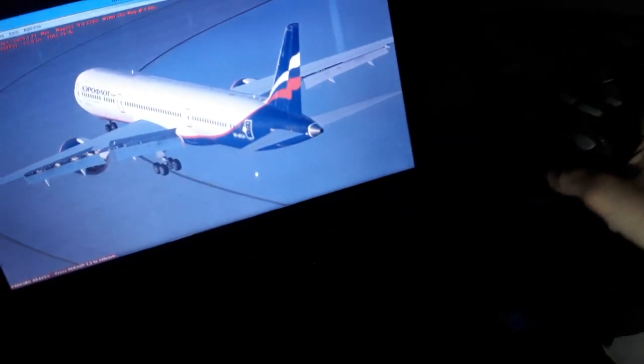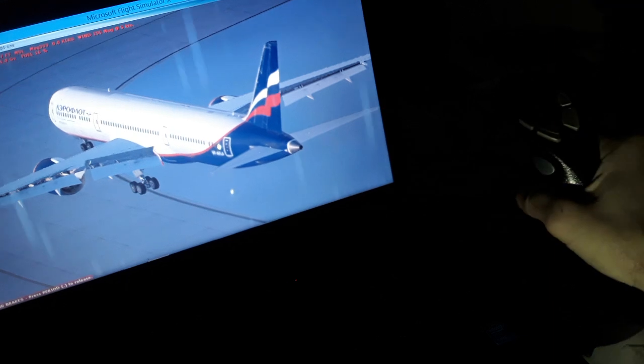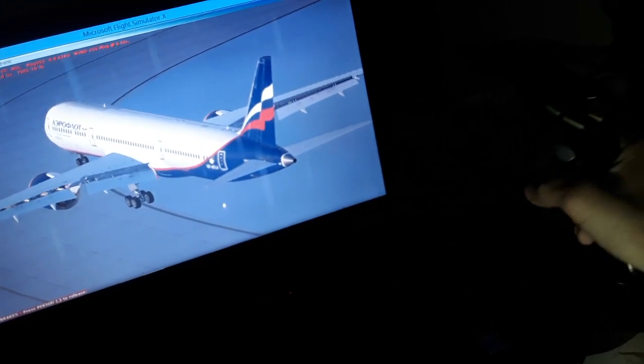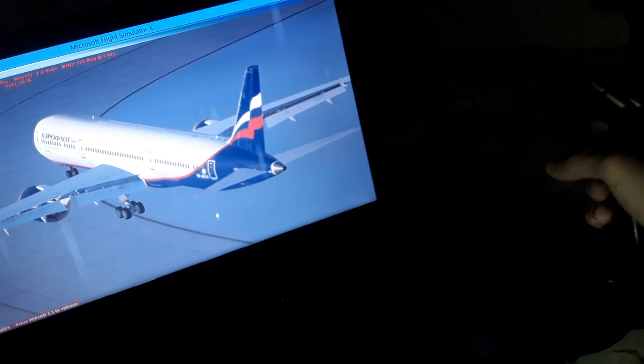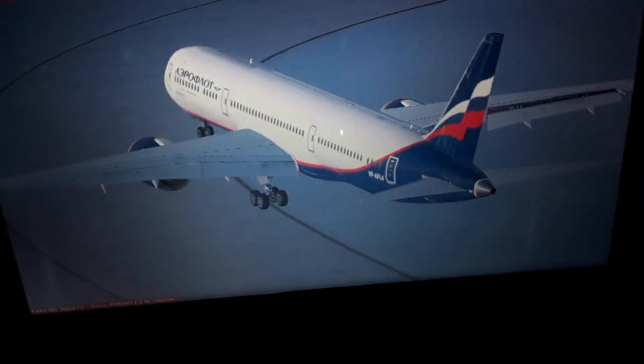We can make in the Airbus the left and right side stick turns. Use the ailerons and the spoilers, inner ailerons and outer ailerons, and also spoilers. So we have in the Boeing the flaperons, ailerons and spoilers instead. So you can see if we use zero deflection, you can see we use ailerons and spoilers, left and right turns, and flaperons.